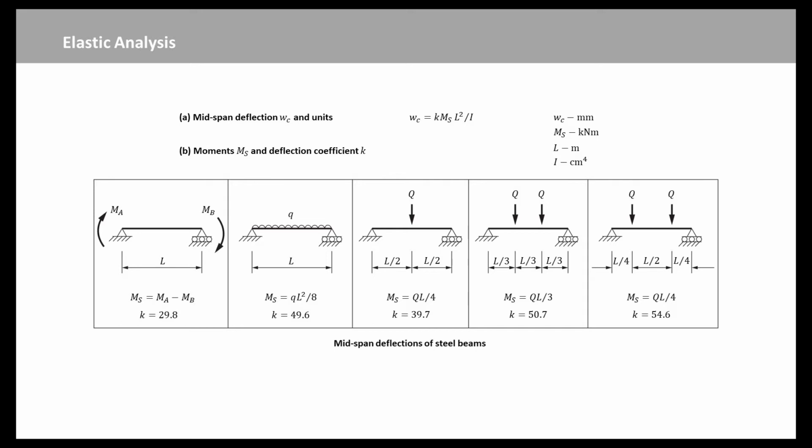In particular, the variation along the beam of the effective second moment of area I of the cross-section is needed to determine the deflections of the beam, and to determine the moments and shears when the beam is statically indeterminate. For this purpose, local variations in the cross-section, such as those due to bolt holes, may be ignored.